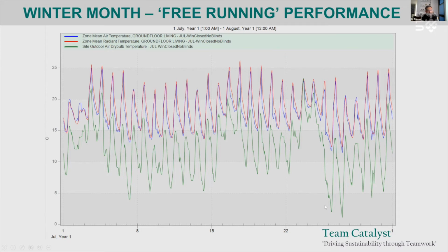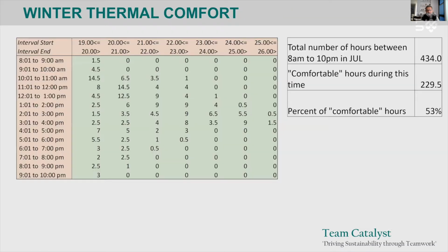The second takeaway is that when it's really quite cold, 2 o'clock at night, my room, that space, is travelling around 12 degrees centigrade. So there's a 10-degree uplift by the fabric, which I'm able to capture. So what I'll do next is take that information and stick it into an Excel sheet, because I've got some criteria that I want to test, okay?